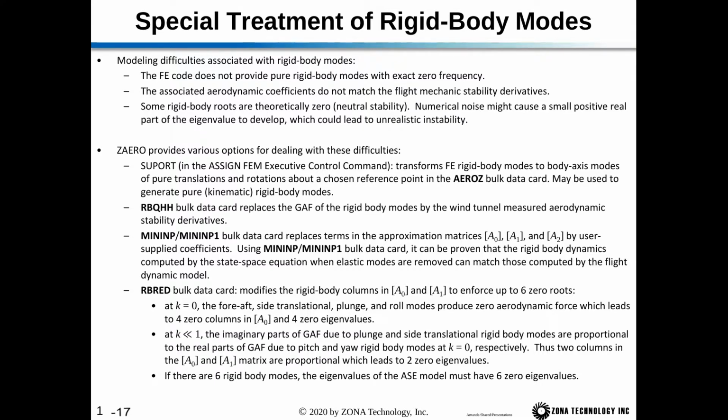So ZAERO provides various options to deal with these difficulties. One, we have the SUPORT option in the ASSIGN FEM executive control command. This transforms the finite element rigid body modes to body axis modes of pure translations and rotations about a chosen reference point in the AEROZ bulk data card. This may be used to generate pure kinematic rigid body modes, and we always recommend using this option.